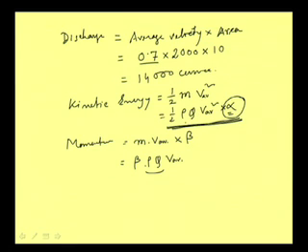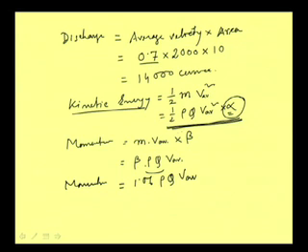So our actual kinetic energy value will be this multiplied by alpha, means we need to multiply it by 1.18. Similarly, beta will be 1.06, and then it is rho, q, and then v average. That way we can calculate momentum. In place of alpha, we need to multiply by 1.18 into this part.